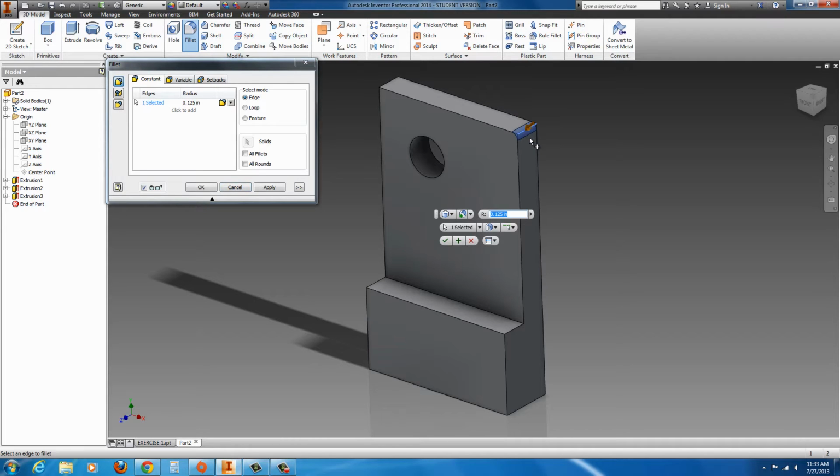So you select that face, and you'll see a little preview in blue. Now there's a little orange arrow there. You could grab the arrow and push it with the left mouse button down and drag it in, and you could see, you could get it to pretty much most average dimensions, or you could type in a new value for it, like 0.75.